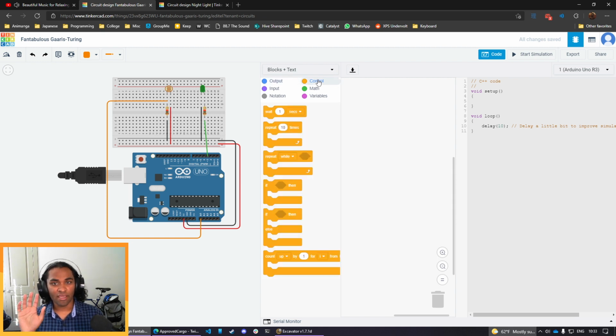So we said, okay, so this is the key word, right? If our value from our photoresistor is less than 512, then turn the light on. Otherwise, or else, that's another key word. So if and else, right? So else, otherwise, if that value is equal to or greater than 512, just making an inclusive range, then we are going to turn our nightlight off.